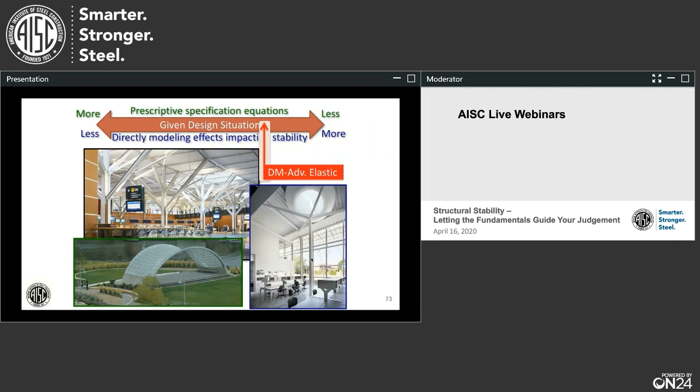You ask yourself, okay, let me calculate the K factor for this column. And you're looking at, all right, oh, wait a minute. That column is going in every direction. No K factor. All right, let me get the unbraced length. Oh, God. Is it the unbraced length of the trunk, one of the arms? All right, I don't know how to do that either. So this would be an example where the engineer might opt to come in and just model the member imperfections as well as the column or the tree imperfections and actually just design for the cross-section. All right, so that would be a case.